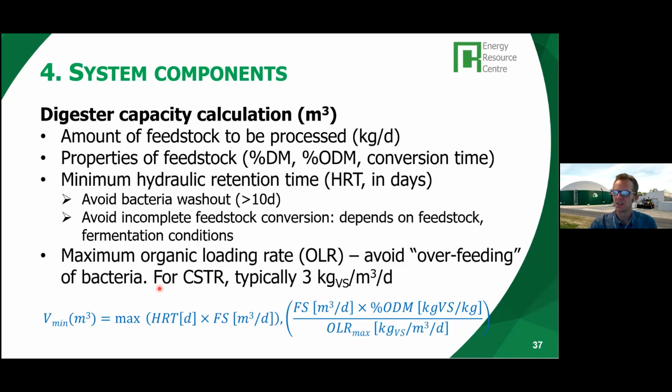And that means that in this case, because the acids build up, you get a drop in the pH in the digester. That may in turn lead to problems with certain bacteria strains, and it could eventually deteriorate, get an unstable system, and you might end up with a process that will stop entirely.